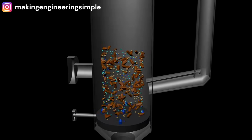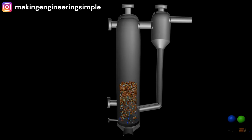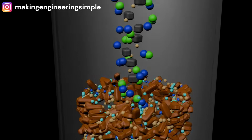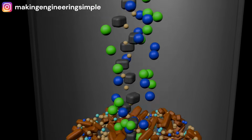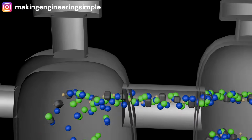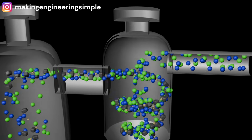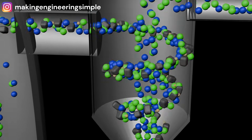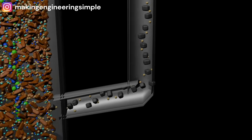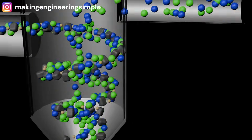This is a fluidized gasification system which heats up a fluidized bed at atmospheric pressure to produce syngas. As syngas is produced, some of the fluidized bed particles become entrained within the syngas. These particles need to be separated, therefore a cyclone is positioned downstream of the gasifier. This allows the lost bed particles to be recycled back into the bottom of the gasifier. Meanwhile, the cleaner syngas is released from the top of the cyclone.